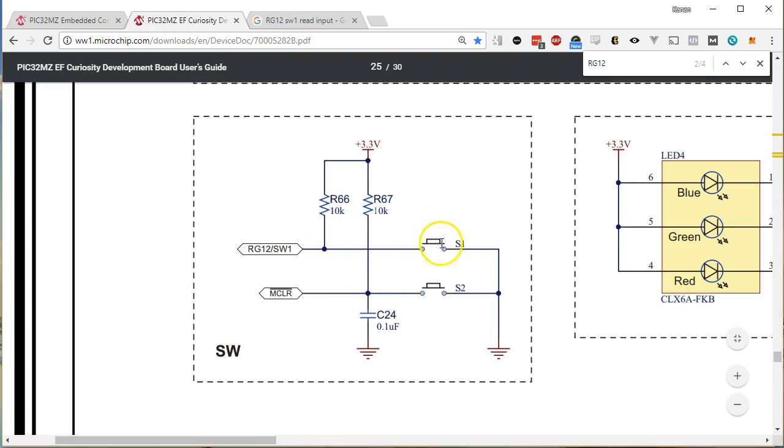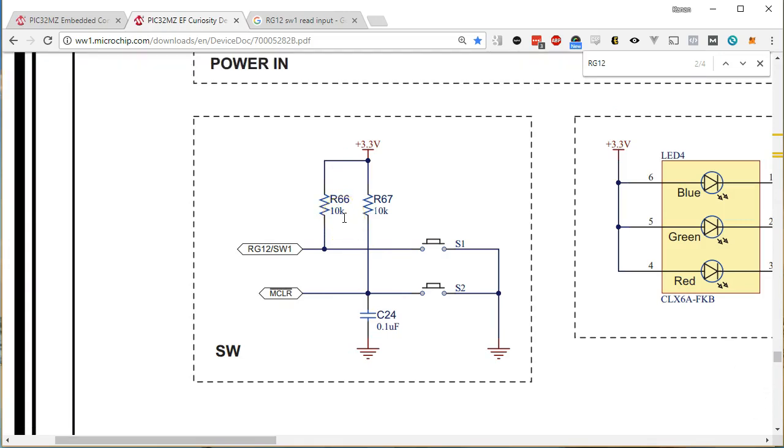And this isn't necessarily the only way you can do it. You could actually do it the other way too, and you could have your resistor here and have your switch here, I think. There are certain configurations you can have that are valid and certain ones that aren't. Like you can run into problems with what they call floating pins, which is if you don't have the voltage on a pin precisely controlled, this is a digital I/O, so it's going to either read it as a 0 or a 1.